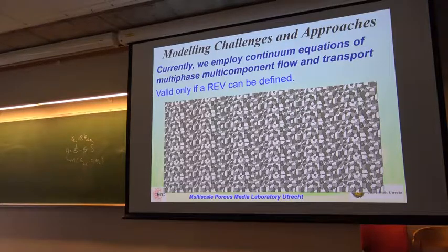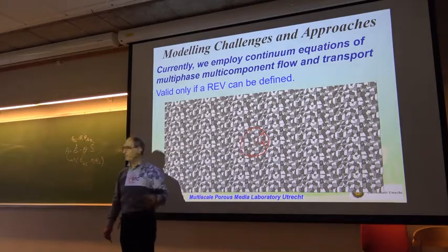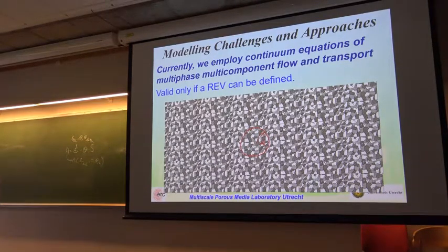You can make it round or cubic. Let's say there is, what is the color here? Is that visible? Yeah, an REV with a given size. Now, as you know, for this REV to give you a representative average value, it must be much larger than grain or pore sizes. It has to have thousands of grains or pores in there. Which means that this R must be much larger than the pore or grain size, the microscale size.